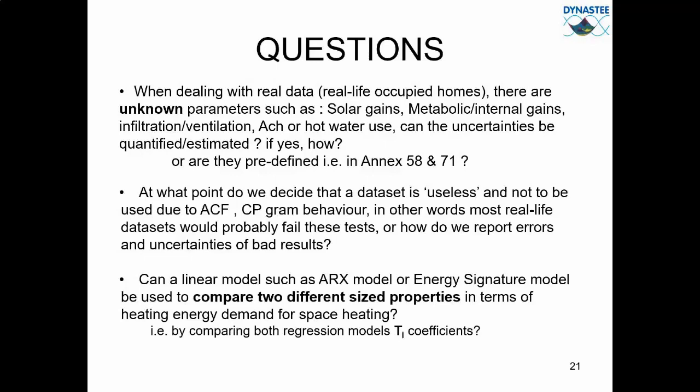So if you have a lot of other heating sources, then you would basically have a lower base temperature, because it shifts that. But the UA value estimate, the heat loss coefficient, should not be affected by this. So there are ways to deal with that.